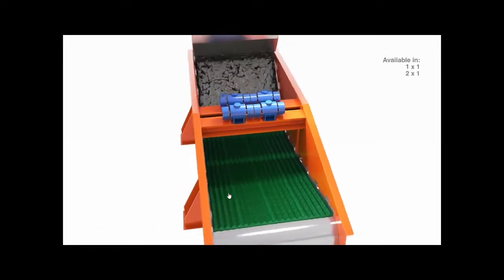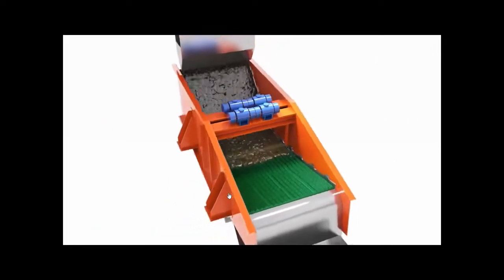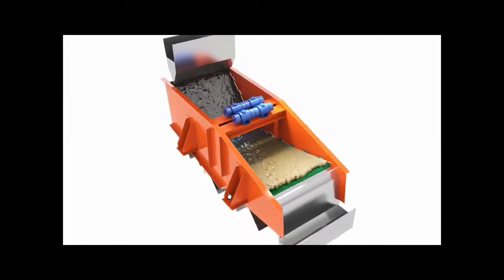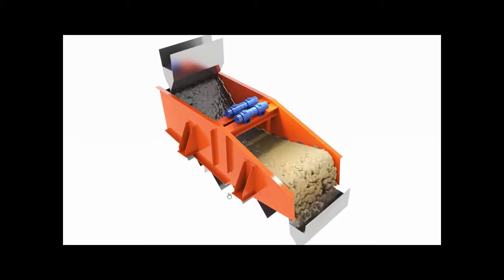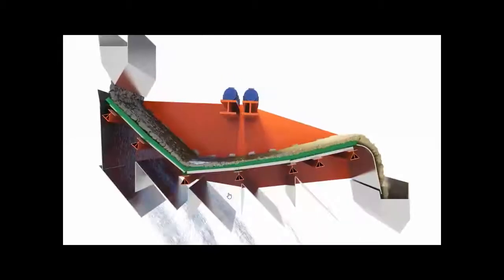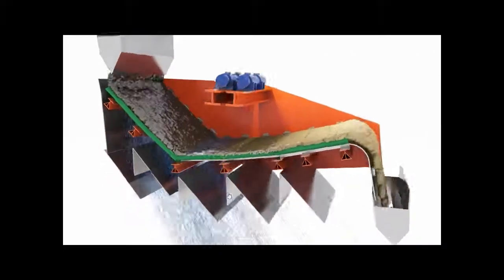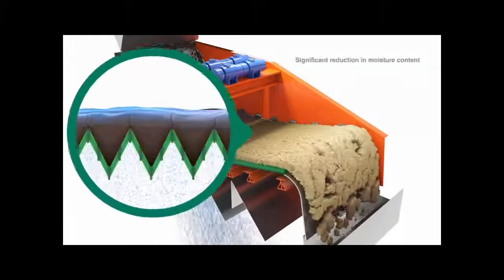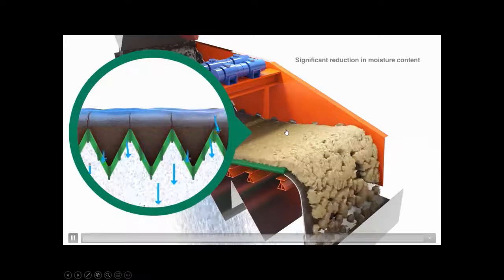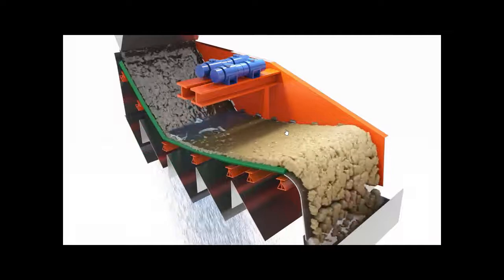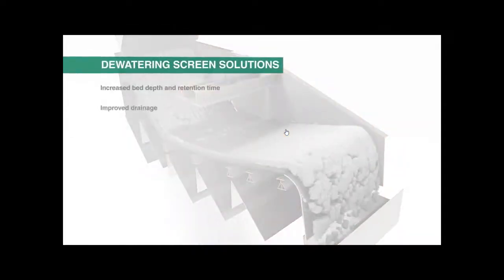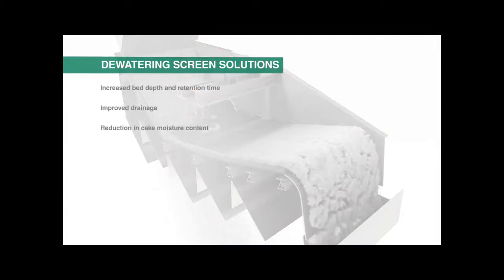The feed onto a dewatering screen normally comes in at about 25 to 30% moisture, and obviously what you're after is a discharge somewhere between 15 and 20%, so it's conveyable thereafter. The critical thing is to get the bed to form outside of the pool area. Another critical aspect is to ensure that you have that open area to do the dewatering in the actual feed area. The TP panel also allows for breakage in the actual bed depth to allow the moisture that's on the surface to be conveyed to the underneath of the screen where it needs to be.